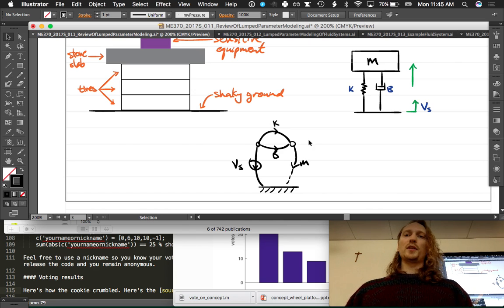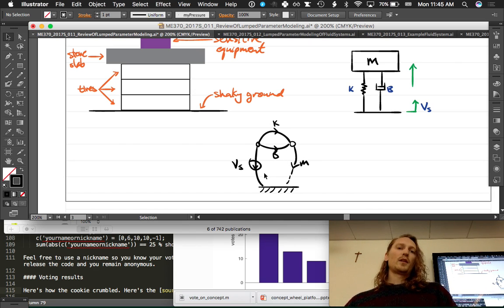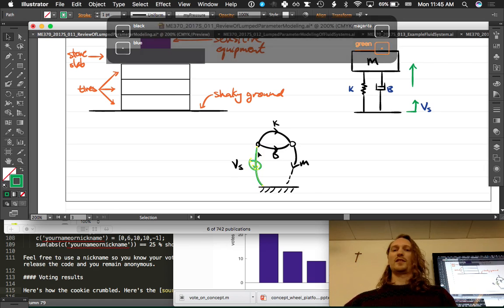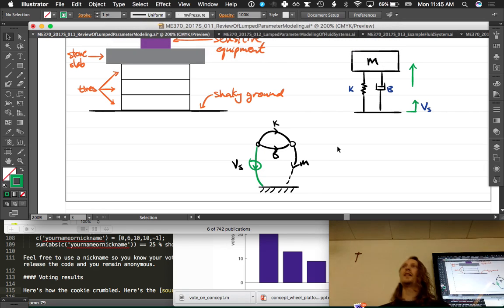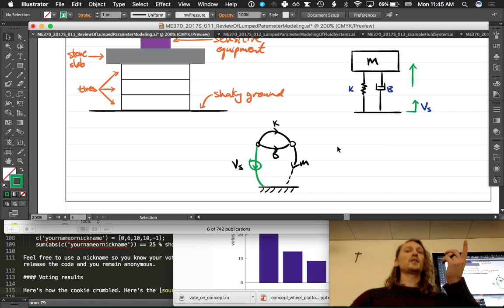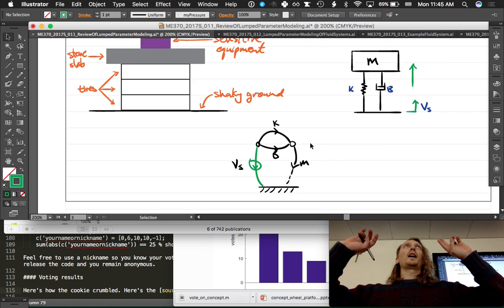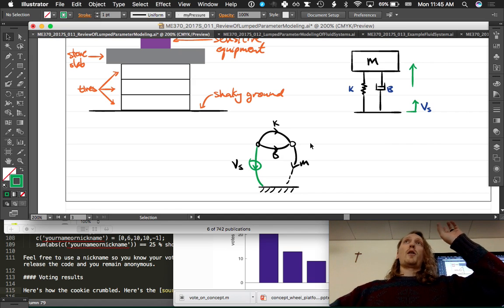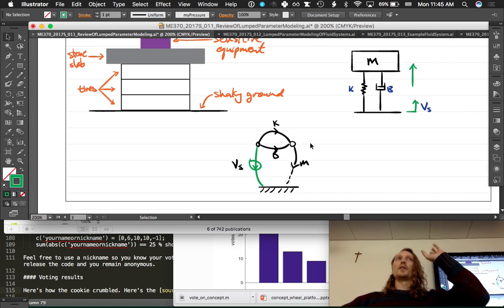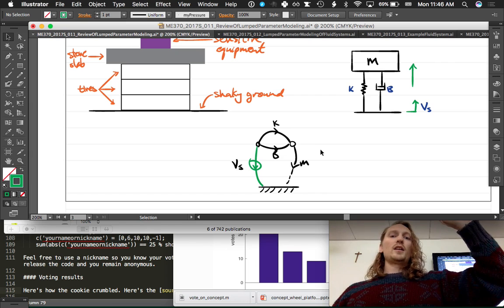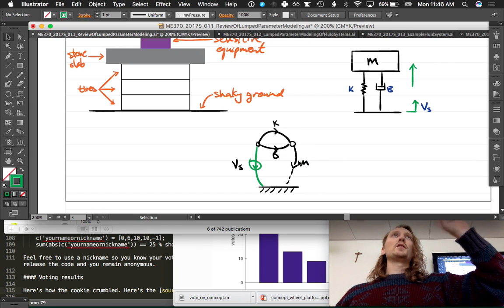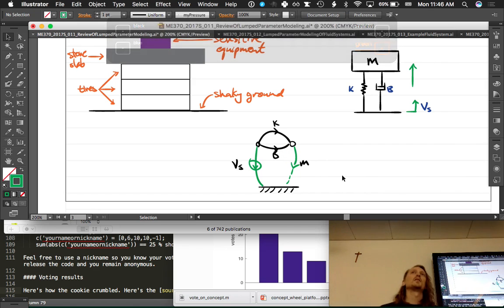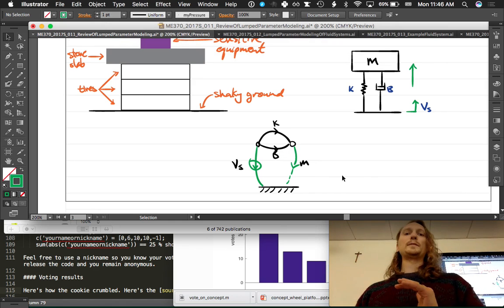All right, so what's our normal tree? That's the last thing we'll do on this example. Across variable sources. If it's a through variable source, we wouldn't select it, but it's a cross variable source. And then, okay, we want energy storage elements of a certain type in the normal tree. First, what is our first priority? A-type, which is associated with cross. So A-type energy storage elements are first. K and M are both energy storage elements. The mass is an A-type. K is a T-type. So T-type is the lowest priority to go in the normal tree.